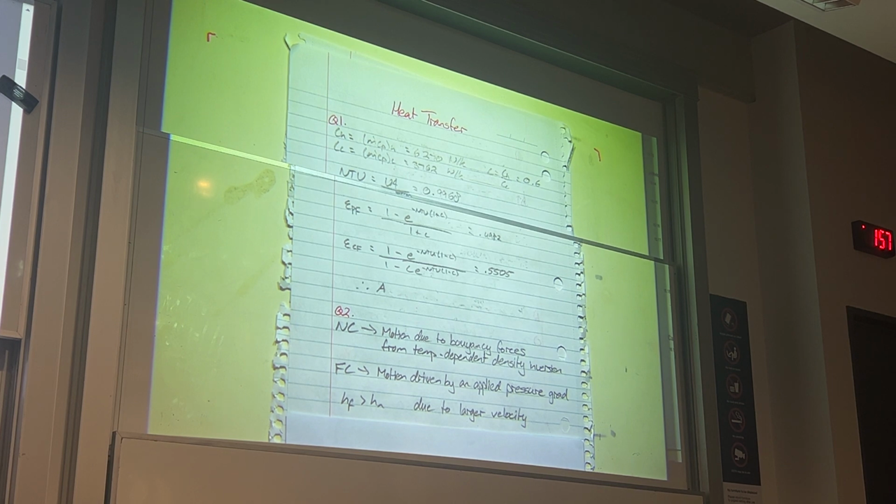We leave it in air, and the air has a lower temperature than the plate, so obviously heat transfers from plate to air. An assumption is, do we want to place the plate on the table? If we're trying to maximize heat transfer, will we have the hot side up or the hot side down?